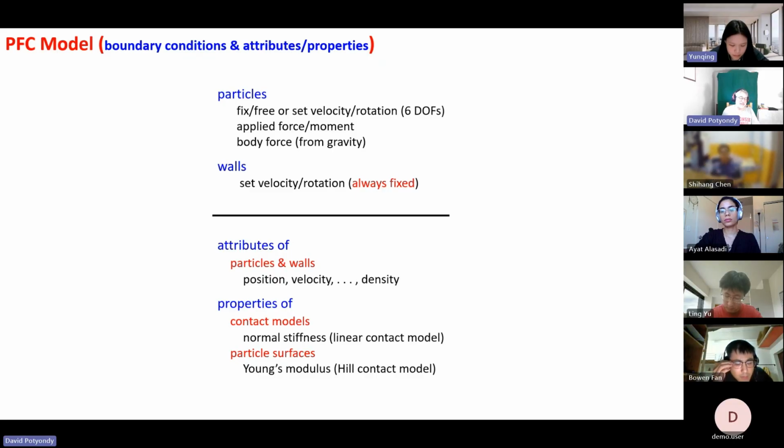Sometimes I might want to say, no, I want that particle to move at 2 meters per second in this direction. So then what I do is I fix the velocity, which means I tell it what velocity, and whatever that is is going to remain fixed. It's never going to change. So if I have a particle here and there's a pile down here, I can say, I'm taking my finger, I'm going to make that thing move at 1 meter per second in this direction. I'm going to fix its velocity, and it's just going to keep moving. And these guys are going to build up forces and do whatever, because that's my boundary condition. Okay. So it's the velocity that I'm going to give as a boundary condition.